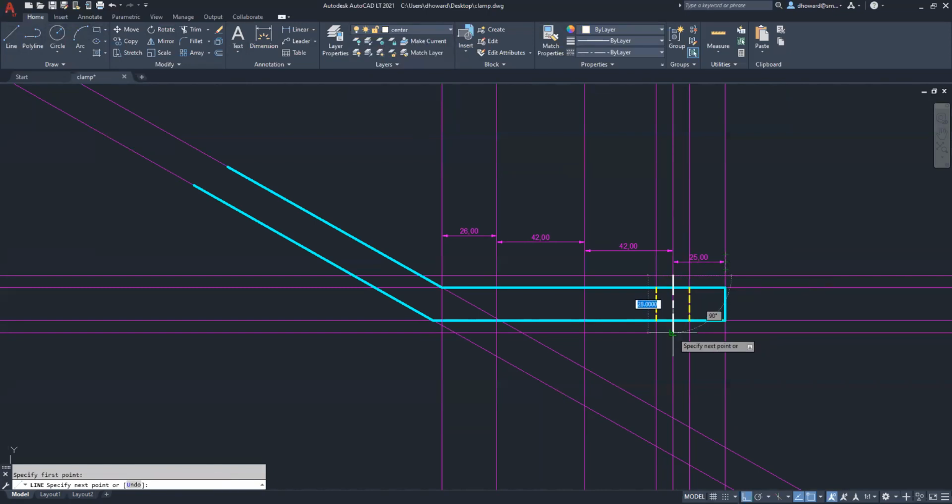There we go. So that's one hole in the side view. Hidden lines were offset 8 on each side. I offset my construction lines 6 on each side to get the length of my center line, and now I can copy those lines from the center, where the center intersects the object line, and place them there, there, and there.